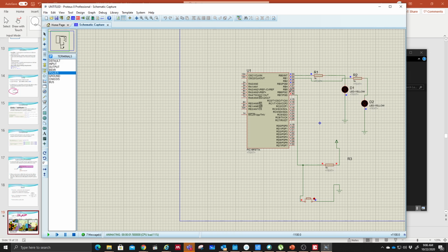So you can see that now it's red, right? Red is because the input is coming from this one. This is 0 volt and this is 5 volt because of here, and the input will be 5 volt. So what happens if I push this button? The value now will be changed to 0 volt. This is a switch circuit, and this is how you have to build a circuit on the board.